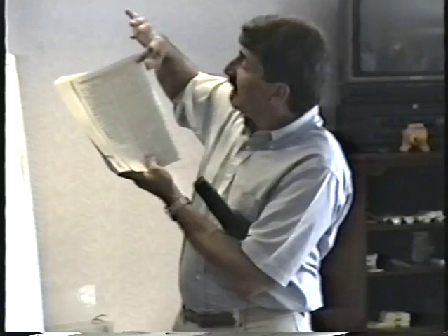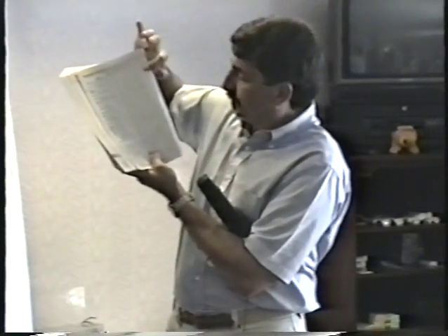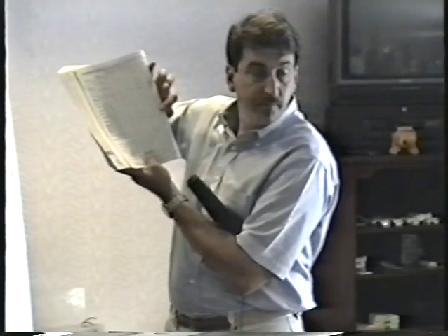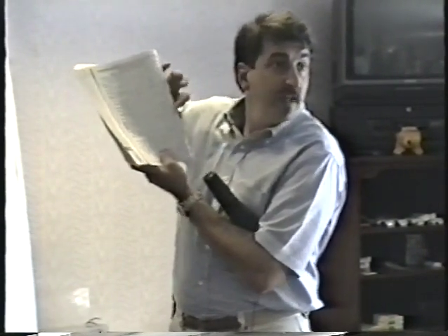Now, look over here, current gain, H sub FE. What's it say? 40. It says 40 typical, right? Well, what was the original gain? 20 to 70, right? 40 is right in the middle, so it's an average. So what they've done here is use the exact same criteria that I just outlined before the break, the substitution method that we just went over. They're doing the exact same thing here, aren't they? So this makes your job real easy. This and your blue book are two very important things to have.